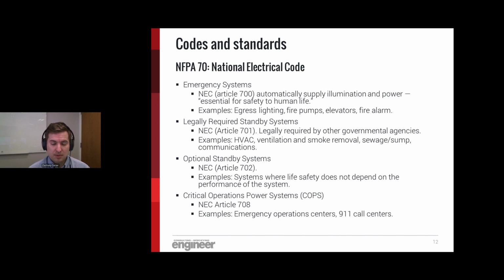So when these loads are stopped, it affects the operation of their business. So while the branch in Article 702 says optional, it by all means may not be optional to what they perceive for their business. Per code, technically, these are not required to start automatically, although that is what we commonly see.